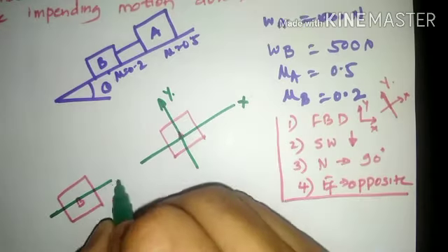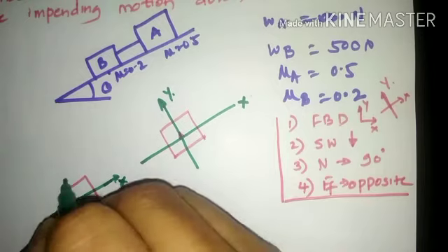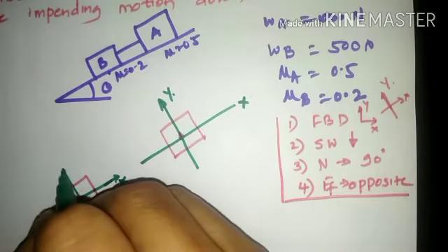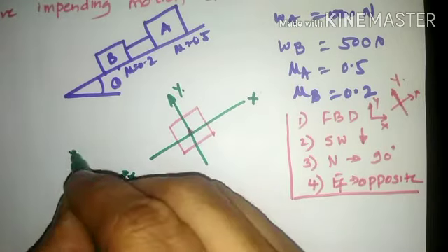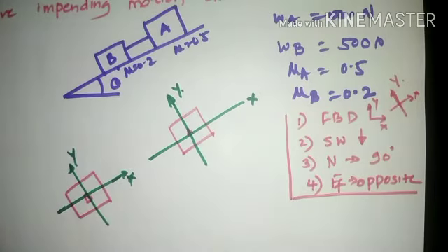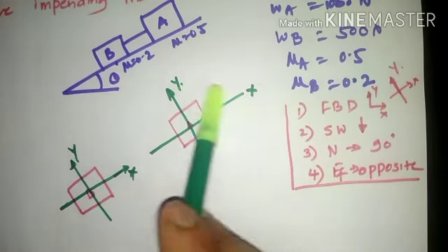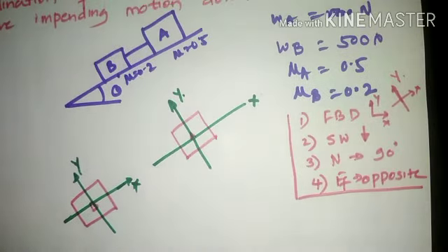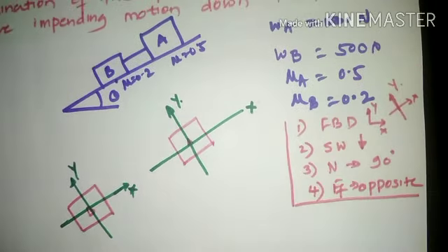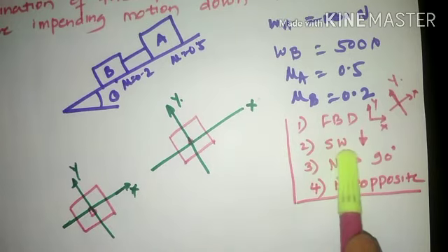Likewise, as you have marked the x-axis here, this direction shall also be called the x-axis, and perpendicular to that will also be marked as y-axis. So these will be the coordinate directions that we need to consider for the solution. That is, when we apply the equations of equilibrium, summation Fx and Fy will be along these particular coordinate directions. Now the next task is drawing the free body diagram. So you have marked the x-axis and y-axis, and we need to mark the self-weight now.